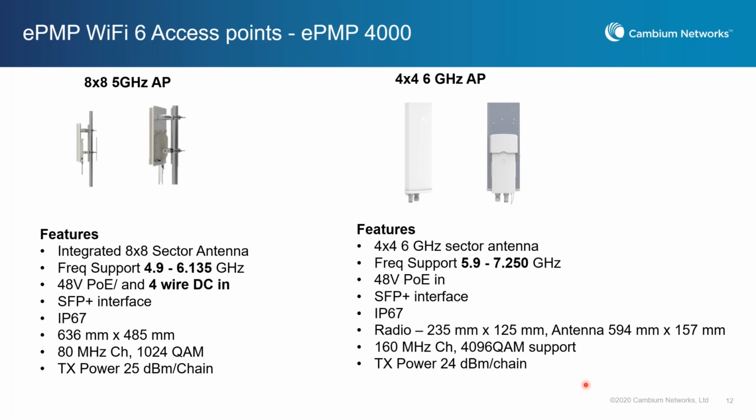And the goal there is that the subscriber module throughput, achieving that higher modulation and getting that high channel bandwidth to operate is a bigger focus. And because the density is not going to be that high initially, and you also have the EIRP limits and stuff, we opted to go with the 4x4 design, manage some of the costs around it. Remember, this is all new chipset, new hardware, so there's costs associated with it, and decided that a 4x4 system will more than suffice in something like a clean 6 gig spectrum